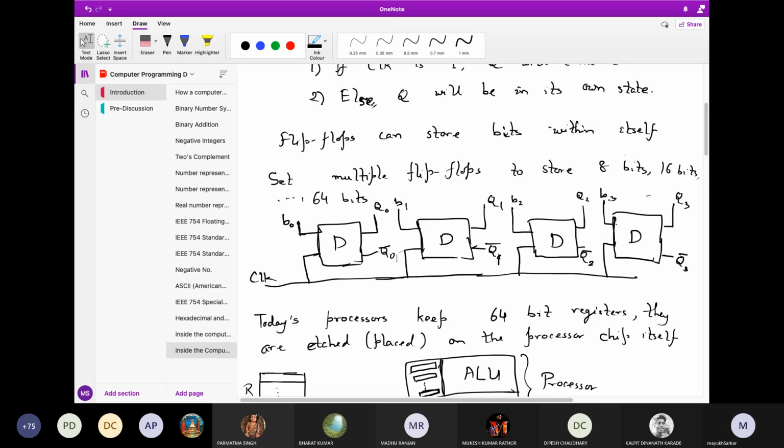Only when the rising edge of the clock occurs, as for example you have considered a machine that works on the rising edge, only then will the memory see the address coming out of the register, because these Q0, Q1 are the outputs from the memory address register, each line. It is only when the rising edge of the clock signal occurs that the memory will see the address.